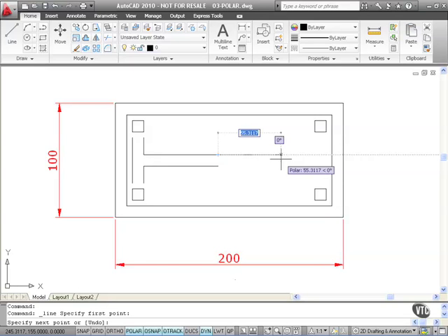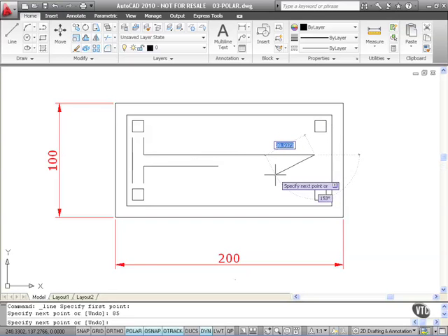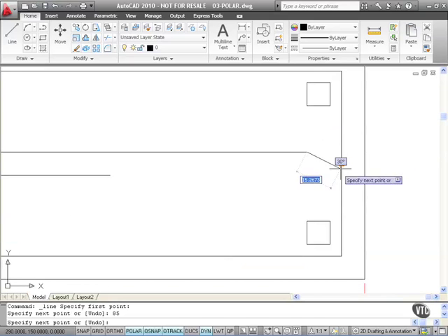Now one of the tricks with AutoCAD is you can type in a distance in the distance box. It's called a direct distance entry. So let's type in a distance of 85 and press enter. We've now used polar tracking to draw a line at exactly 0 degrees that's 85 units long. So that ties in nicely now. Can you see that with our squares there? Now I'm going to zoom in a bit and roll upwards on the wheel mouse a little bit so that we've got a bit more detail.